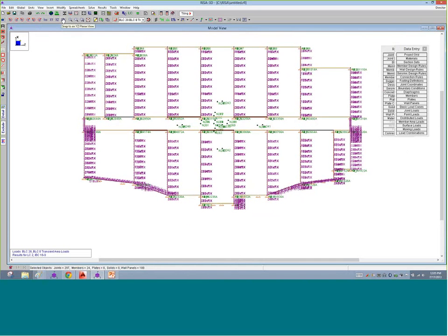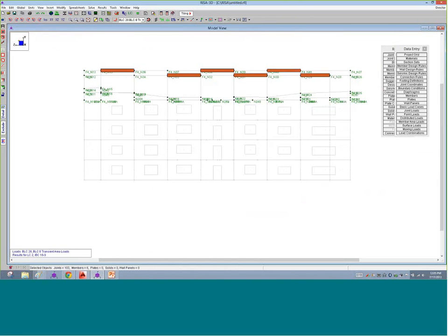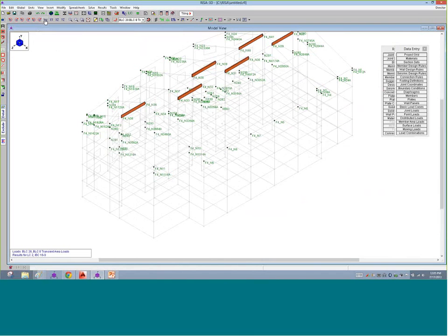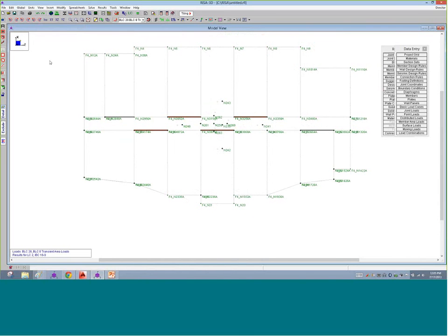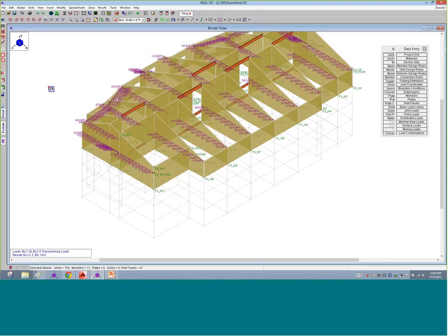Now if I pop to the top of the structure, let's only select the very top of my structure, or the roof level, and look at that here. Let me make sure I grab the right thing. I'm going to use my selection tools and select the whole wall structure up there, and look at this in isometric view. What I see here is that at these wall levels where that hits, I get those loads applied to the wall.